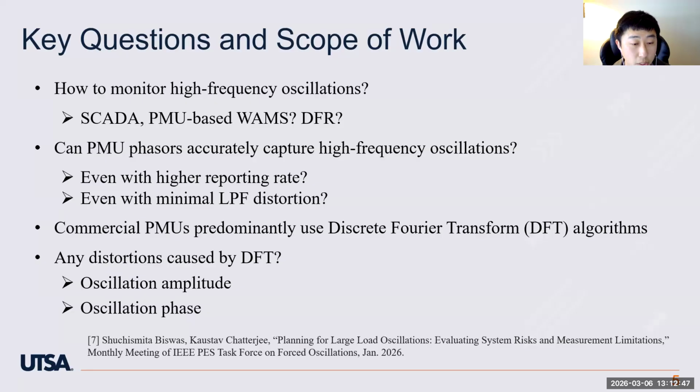We know that other phasor estimation methods can also be used, such as least square, Prony, matrix pencil, Kalman filter, etc. But those are not covered in this study. So we are focusing on DFT-based phasor estimation in this talk. But if a PMU is using another algorithm, similar studies should always be conducted to verify their accuracy and their effectiveness when dealing with high frequency oscillations.